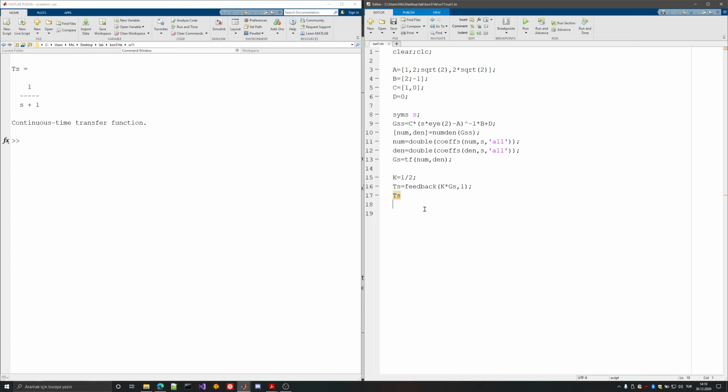But in the case of a state space feedback controller, we will use k1 times x1, k2 times x2, the sum of this, and we will feed this back. This is not the error feedback, this is the state feedback. So they are a bit different, and this may have some advantages or disadvantages, we will see. Now, how can I try to design a state feedback controller? Well, basically the Ackermann formula helps us. Let me just use the Ackermann formula here.